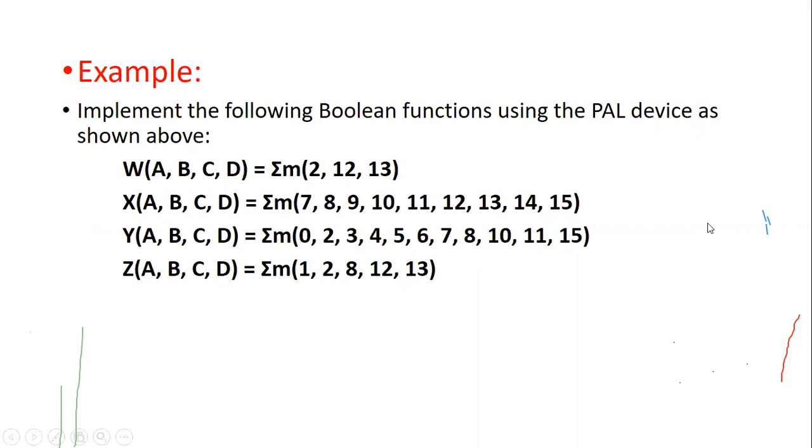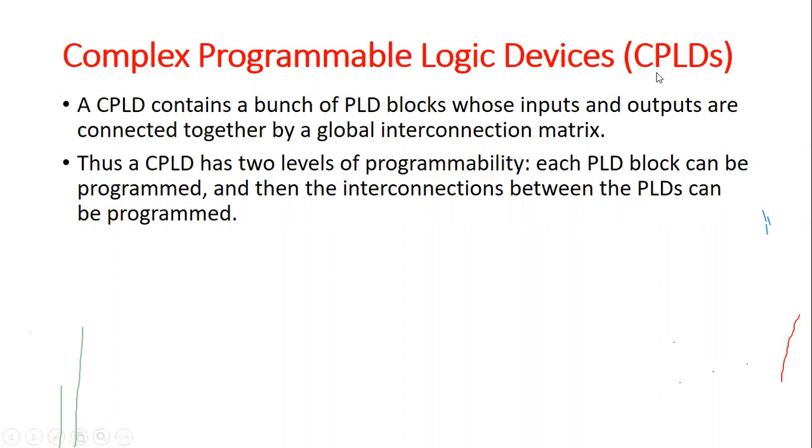in these memories, which are CPLD and also FPGA. So we have been discussing programmable logic devices up to now. Programmable logic devices here means those are all nothing but the SPLDs. What is meant by SPLD? Simple programmable logic device. Simple programmable logic device means, for example, if you want to implement any simple combinational circuits or any circuits, we are going to implement those by using simple programmable logic devices. That is either by using PLA or by using PAL or by using PROM.